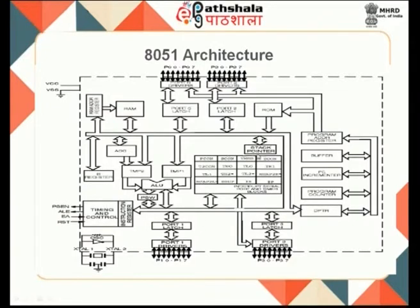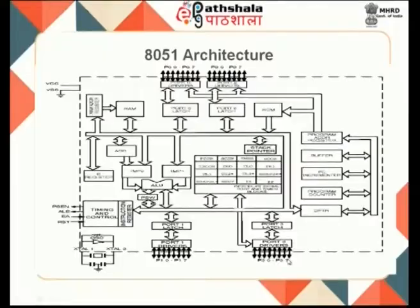Other than that, we have 4 ports, P0, P1, P2, P3. All these 4 have an 8 bit communication line. So, parallel ports are available, and we have an oscillator. This oscillator provides the clock for this particular CPU, which in turn synchronizes the machine cycle.